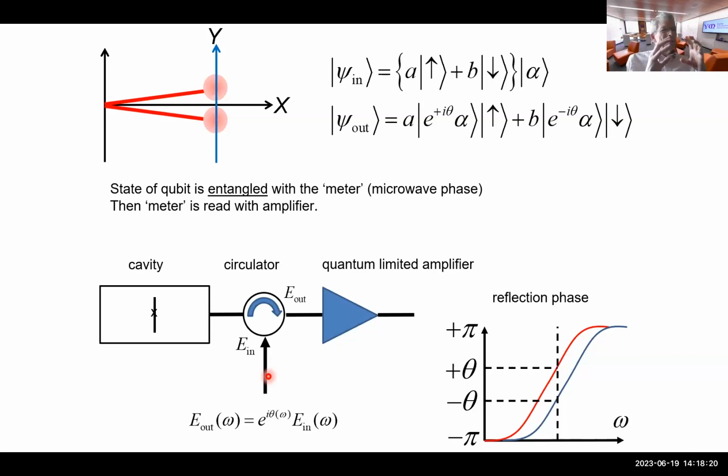Then for the purposes of doing quantum error correction or quantum computation or quantum simulations with bosons, with microwave photons, you want very high Q cavities because that's holding your logical information. And the purpose of the transmons is just to help you manipulate it and measure it. So a typical setup would have a high Q cavity, probably, at Yale, they tend to be 3D cavities, and also in Pittsburgh and other places. And then they may be coupled to a transmon. And then there might be a 2D coplanar waveguide resonator that's used for the readout.